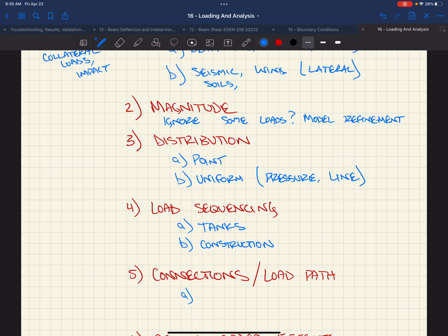So what do they do? They pump water out of wells and put it in a big storage tank way up on the hill, right? We get hydrostatic pressure from that. It's like Belgrade's water tower, but you use natural topography to get it. Instead of putting it up on a tower, you're just putting it up on the hillside, right? So you have to design for that. Any thoughts about how that works, or what would be important about sequencing of tanks?